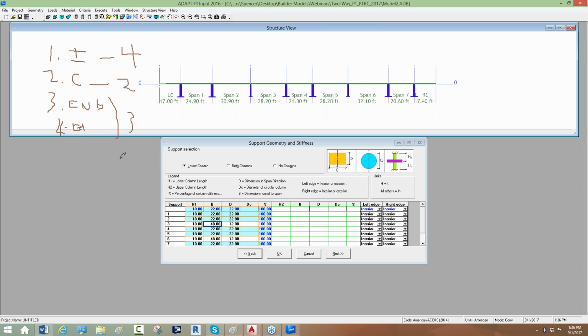So the end section, if I have a slab here and I have a column, and you have bending, let's say there's an axis here and an axis here. If I have bending about this axis, I'll call it X, and this is Y. Bending about X would be the edge condition. Bending about Y would be the end condition. So the program checks both of those at end/edge conditions. In the plane of the slab, the program can determine basically two pieces of the puzzle. So there's four pieces of a puzzle it's trying to determine. It can determine two, let's say.